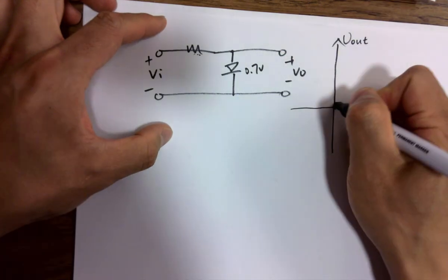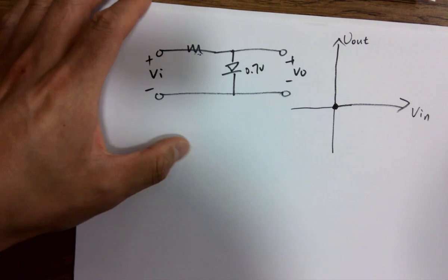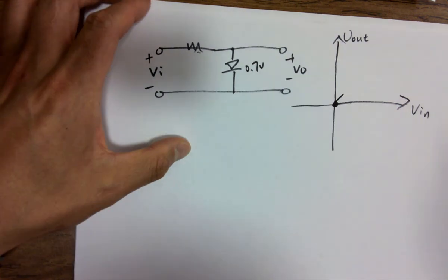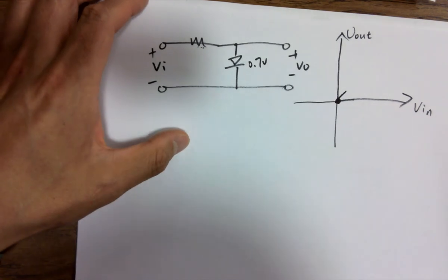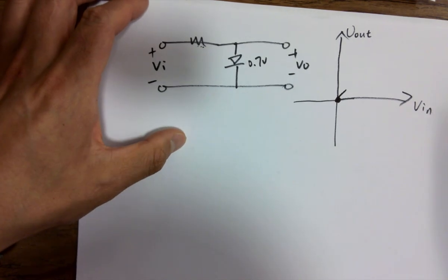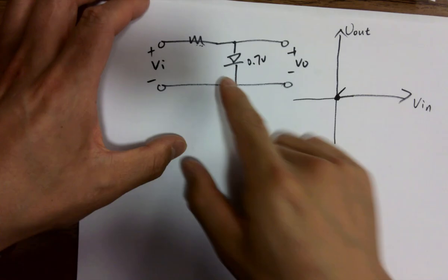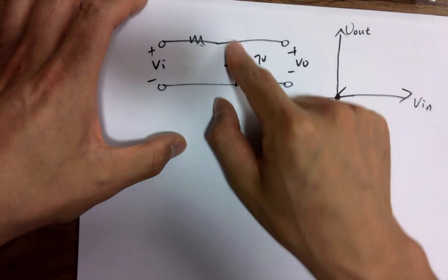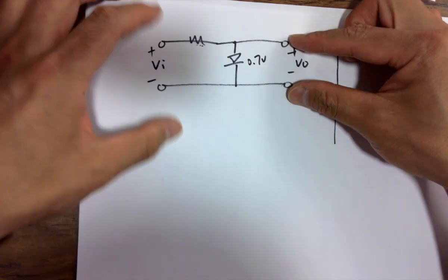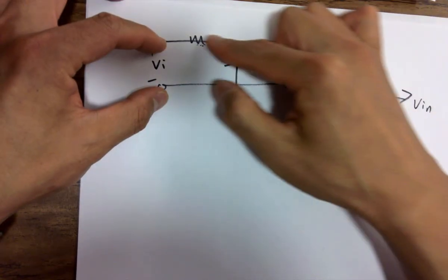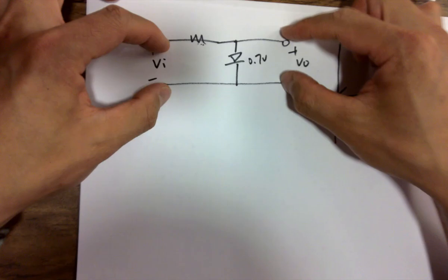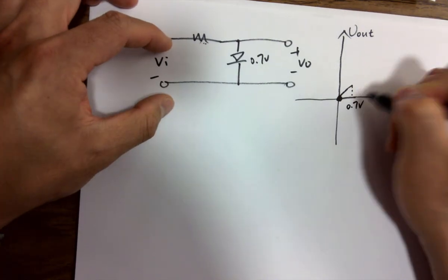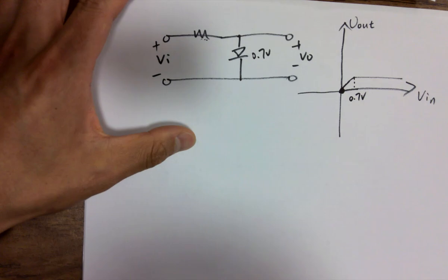So we start V in from 0 volts, right? 0 to 0.3. You agree with that? Why is it linear? Because you haven't hit the threshold yet, so there's no current going through the diode. No current, no voltage drop. This is disconnected, so whatever is here, it's linear, until 0.7. What's going to happen? Flat, right? So where does the voltage go?